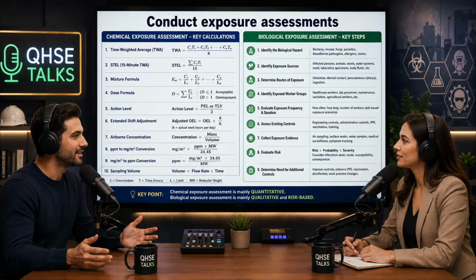The sources contrast two specific technologies, diffusion tubes and vapor monitor badges. Diffusion tubes, frequently called colorimetric detector tubes, are essentially chemical litmus tests inside a sealed glass tube. How do they work? The tube is packed with a specific chemical reagent. You snap the glass ends off, insert it into a calibrated hand pump, and draw a precise volume of workplace air through it. And the air reacts with the reagent inside. It causes a colorimetric stain. The chemical reaction turns the white powder brown, or the blue powder pink. The length of that discoloration corresponds to scale markings printed on the glass, giving you a direct reading in parts per million.